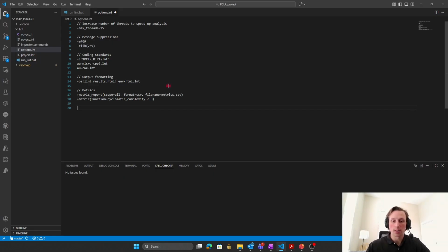The next option I wanted to show off from that kind of metrics perspective is a stack usage report. This report is just going to contain worst case stack usage for each function within your program. To enable this report, all you need is the +stack option, and it's going to have one input parameter, and that input parameter is &file.